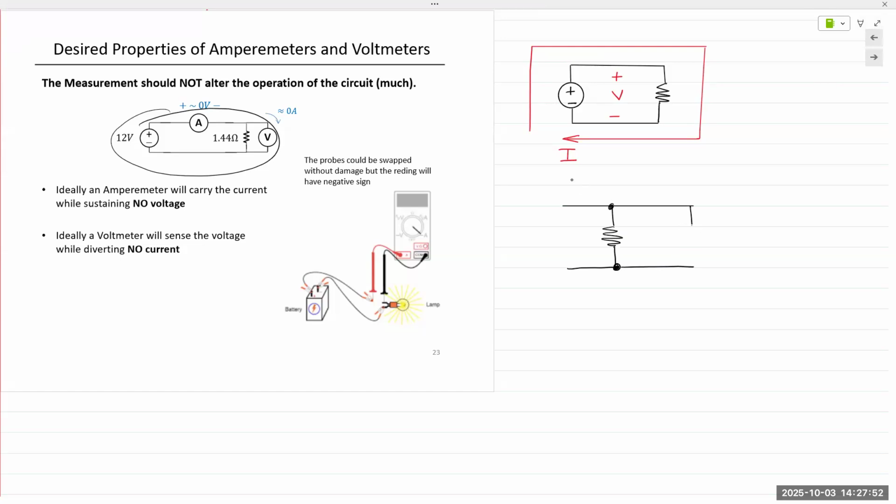All electrical devices can be represented as having resistance at their two ends. So if you take a voltmeter and connect it in parallel to a resistor to measure the voltage, that circuit is going to see the resistance of the voltmeter also. So what happens if the resistance of the voltmeter is low?